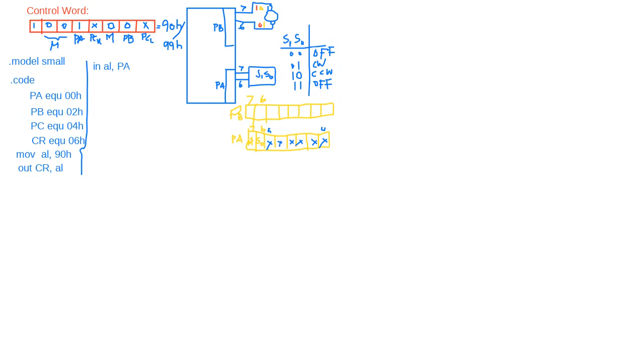If we make the AND operation with all the other bits 0, then they will be 0. Only S1 and S0 will stay what they are. So this is the AND operation, and it is the way we can mask off the other bits, 0 to 5.